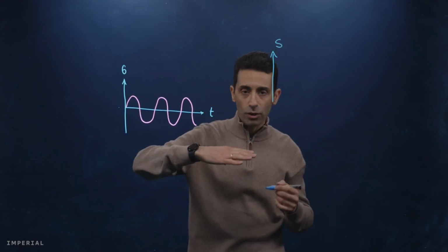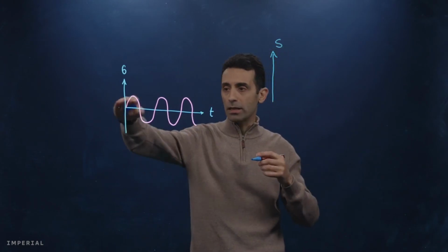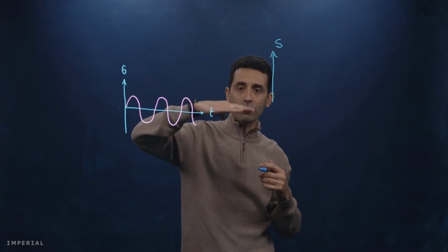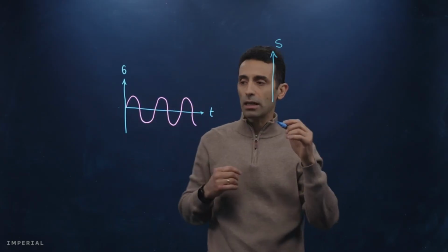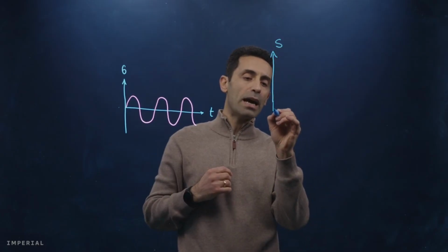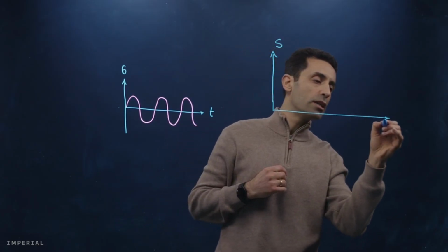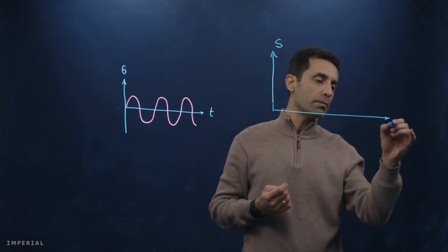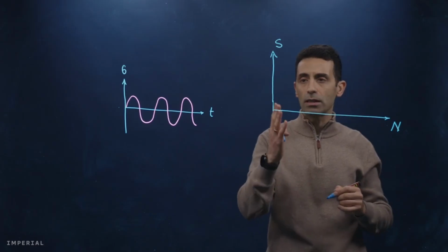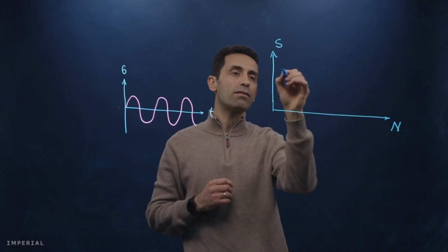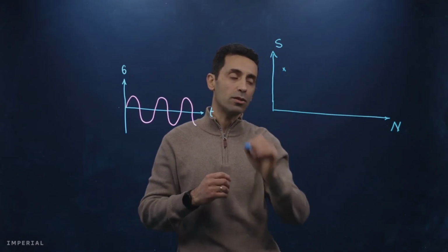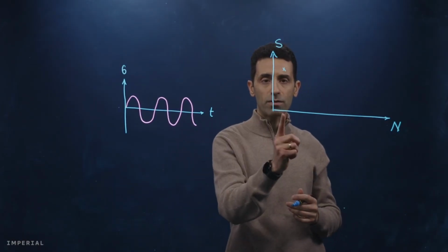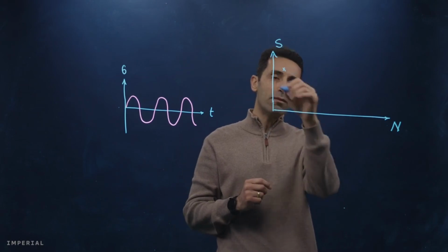This is the load that we are controlling, so we are increasing the peak of this load gradually, and then at each fixed value of that we continue the cycles until it breaks. And we can have on this axis the number of times that we are applying that cyclic loading. So imagine if we had fixed this value at this magnitude, and then we apply the cyclic loading and it fails at this number of cycles, then we have a point here. And then we continue that.